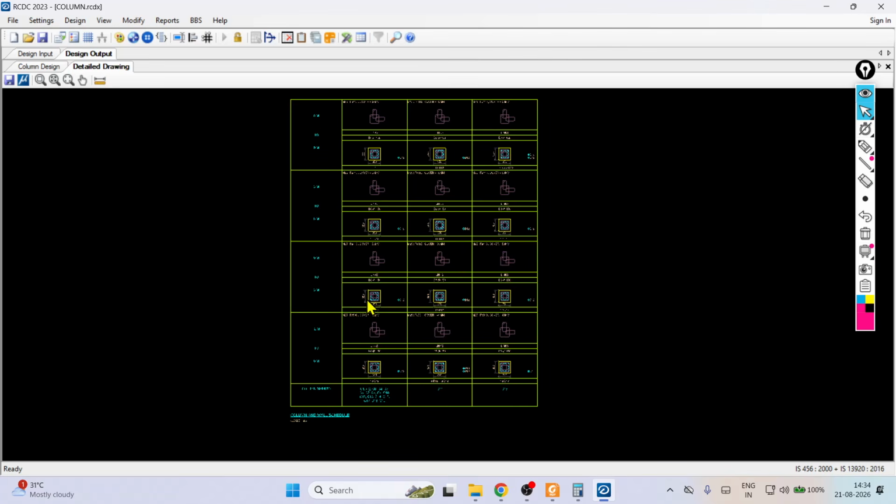You have to go for the special kind of stirrup. If you are going for the ductile detailing, then we have to write only that the stirrup spacing is less than, for L by 3 we have to provide less spacing of stirrups. Otherwise, if you are not interested in ductile detailing, the same spacing everywhere.